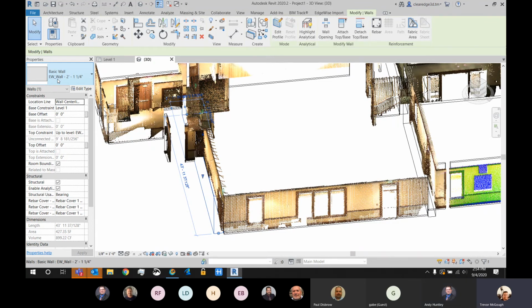So for example, larger pieces of structural steel or wall surfaces, you can have a lot less data because those are basically a lot bigger objects. Smaller pieces like pipes, smaller conduits, stuff like that, then I would definitely say you need more data just to ensure you have a good amount of coverage and enough density to trip the algorithm. So again, it depends on what you're scanning.